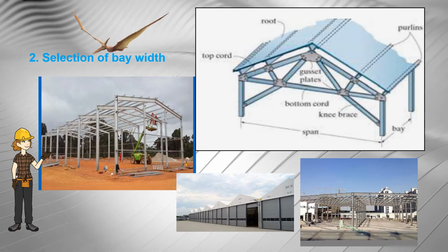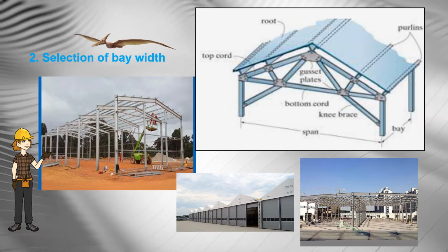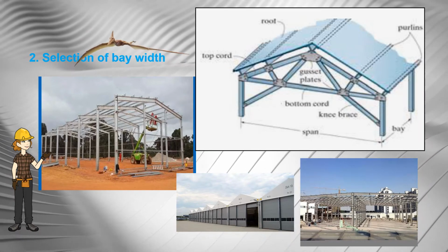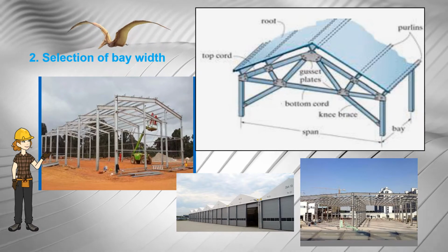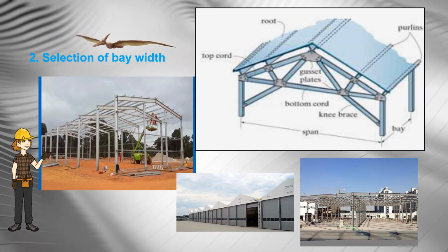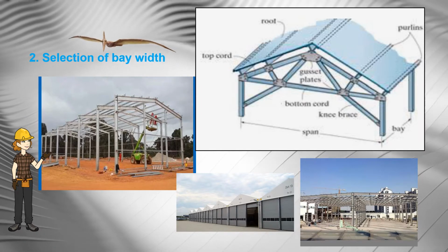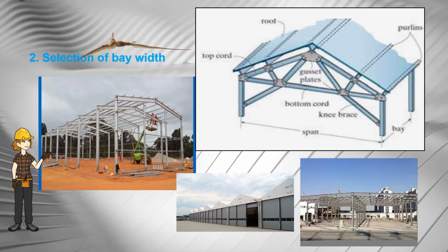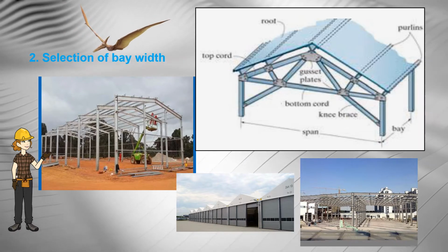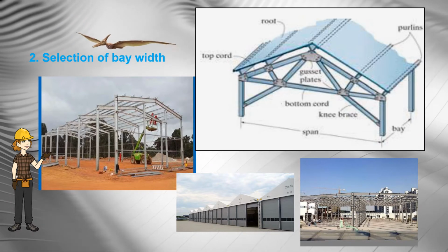In most cases, the bay width may be dictated by owner requirements. Gravity control generally controls the bay size. For crane buildings such as light or medium cranes, bays of approximately 4 to 8 meter may be economical because of the cost of the crane gantry girder.